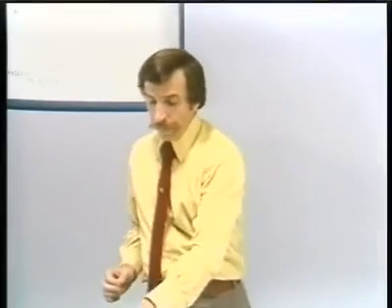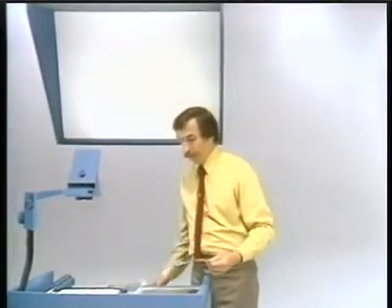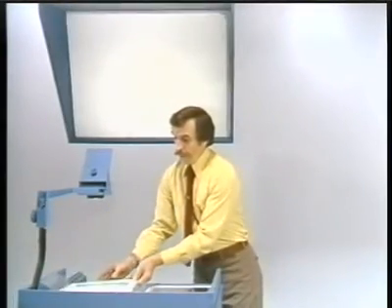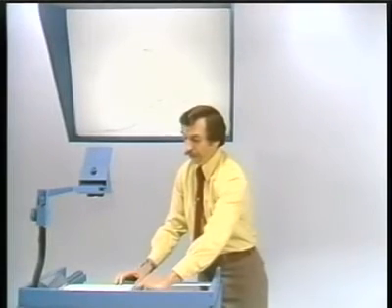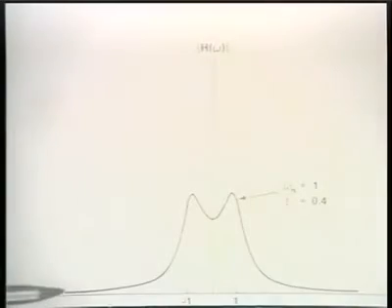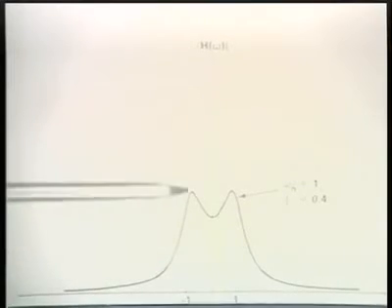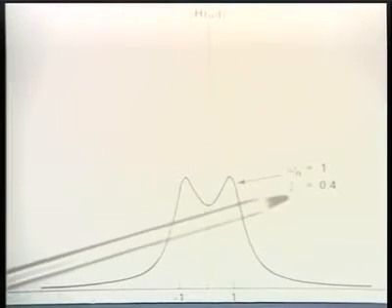Okay, so for complex poles then, for the second order system, what we see is that we get a resonant kind of behavior, and in particular that resonant behavior tends to peak or get peakier as the value of zeta gets smaller. And here, just to remind you of what you saw, is the frequency response with one particular choice of values.